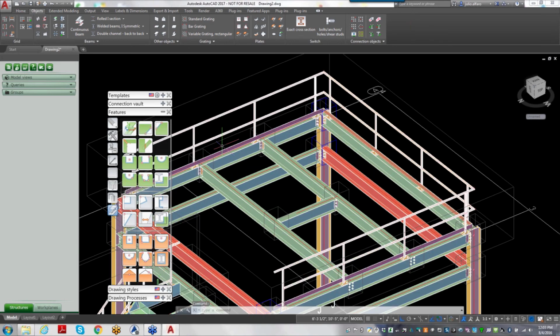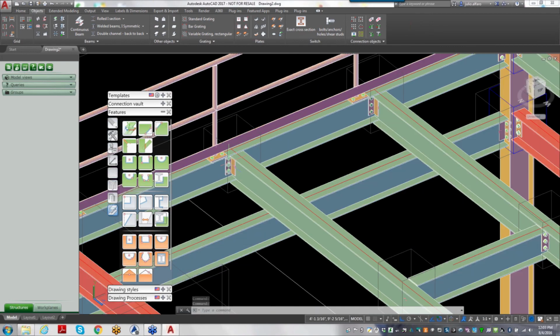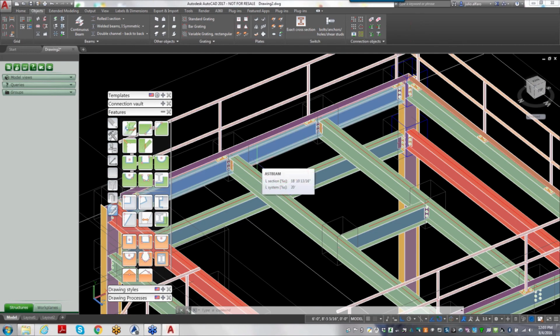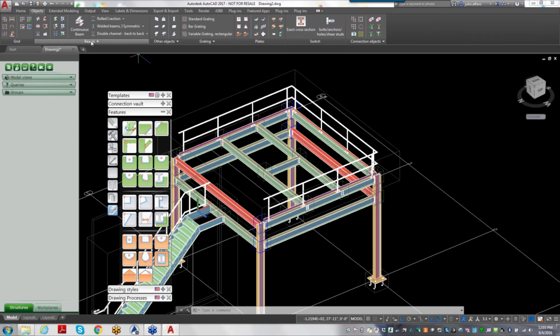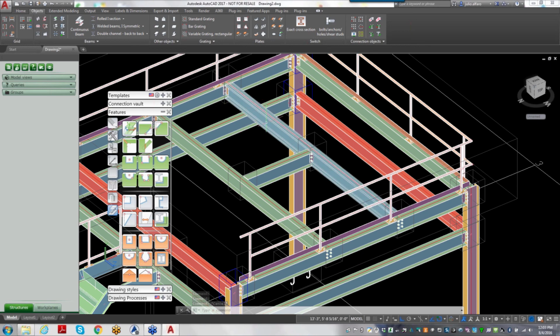But if you need a connection with plates, angles, or anything like that, Advanced Steel can produce that a lot faster than the frame generator can. Now, the frame generator is done through lines. Advanced Steel can turn lines into beams, just like I showed you on this one. This is literally a frame, right? I selected those lines and turned them into beams. We do the same thing with columns. So there are similarities, and there are advantages with Advanced Steel when you get bolted connections, and at the same time you can also do welded connections if needed.